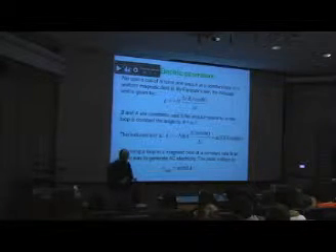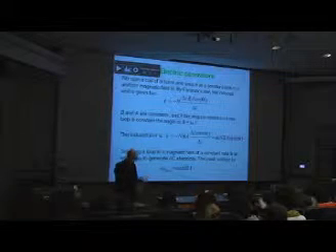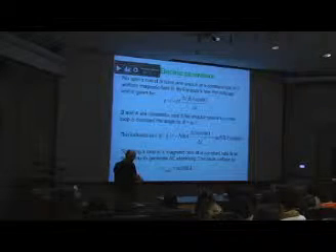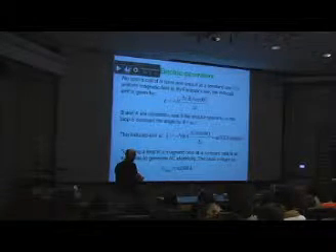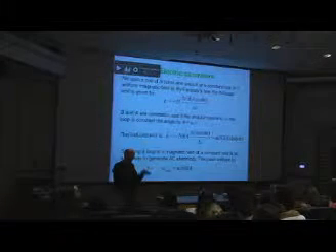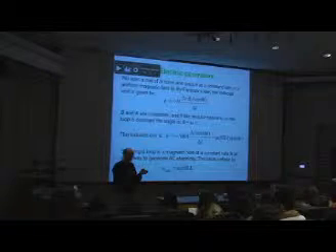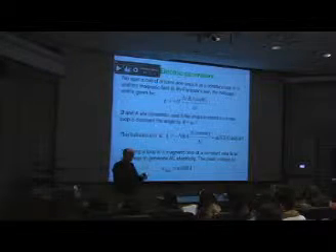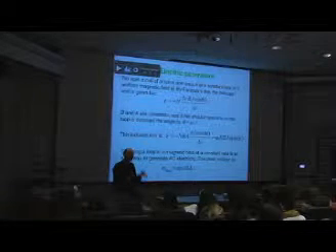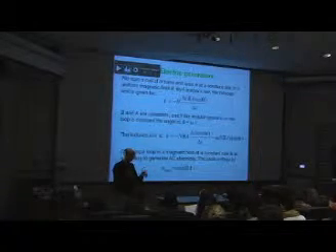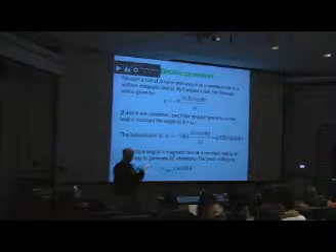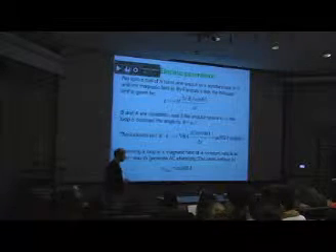So on the pre-session quiz, what did we do? We gave you omega, we gave you N, we gave you B, and we didn't quite give you A. That was one problem that some people had, I think you just assumed it was A, but it wasn't A, right? So we actually gave you the length of the square thing. You got a square thing, you got a length here, you got another length there. Multiply those together. And also it was given in centimeters, right? So you got to convert to meters. So don't forget that it's length that we gave you in the pre-session quiz, and it's area in the equation, and convert to meters. Okay?